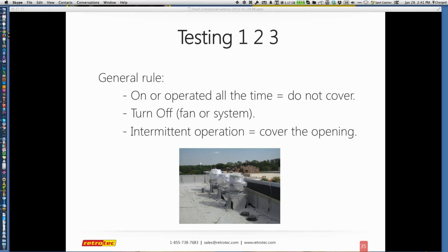There, we're more interested in how the building performs, and those are the values that we would use in any energy analysis program. So my thought is that if we have an exhaust fan that's running most of the time, we would call it a device that supplies flow, and that would be entered into the calculations as a device that is causing flow to either pull air into the building or blow air out.